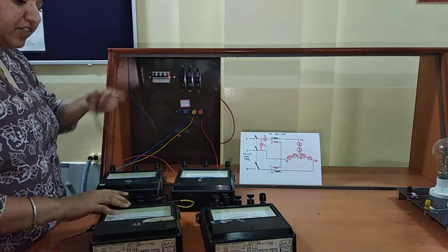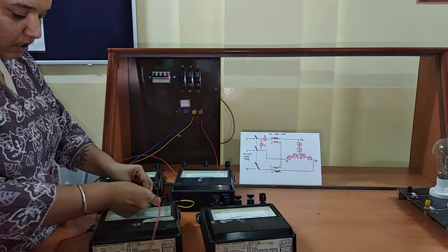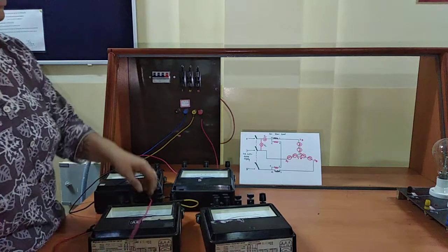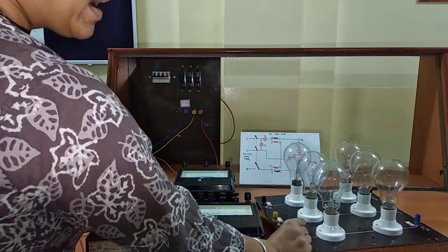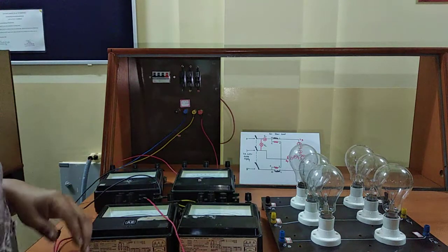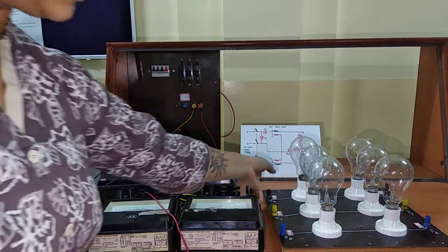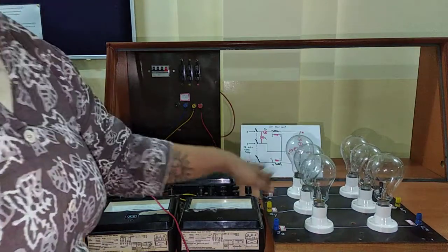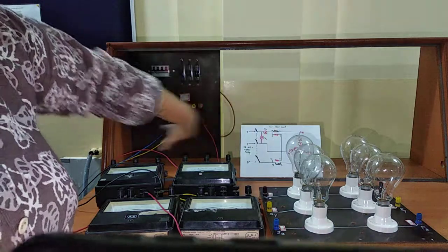Now, after we have mains and common connected, further with the load terminal, we will connect it to the point where we have the load: SR, FR, SY, FY, SB and FB. So this is the resistive load that we have taken, in which we have the points SR, SY and so on, right? Since we are doing this experiment for star connection first, let us connect this part of the circuit in star and then connect it this side.